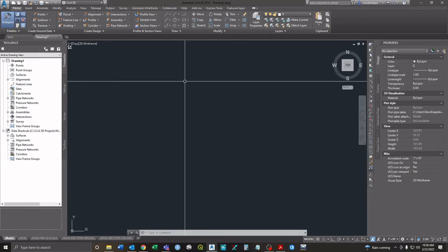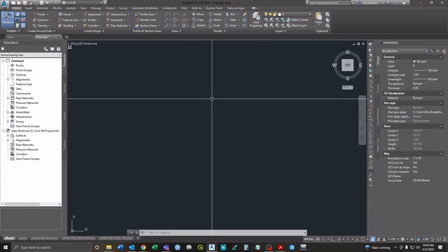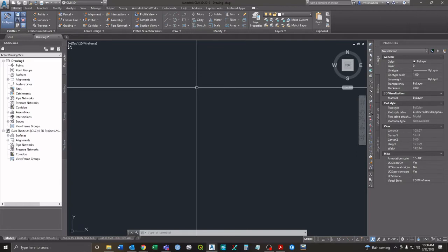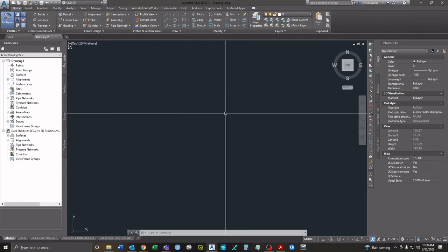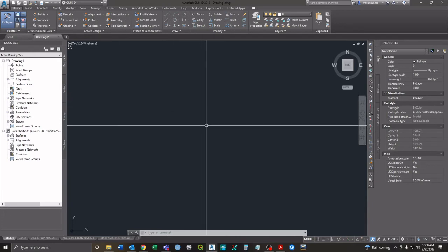There are ones for feet or meters, or most of what our surveyors use, which I'll go back through, like Oklahoma State Plane. Then you have to set a datum, which is basically the shape you think the world is, and the coordinate system is based on what the numbers mean in the XY direction for the local area.